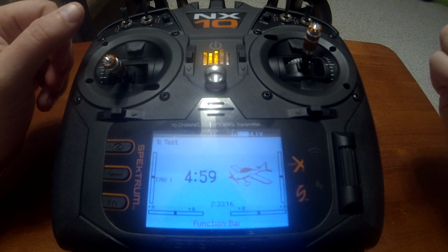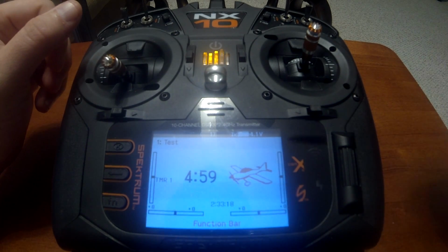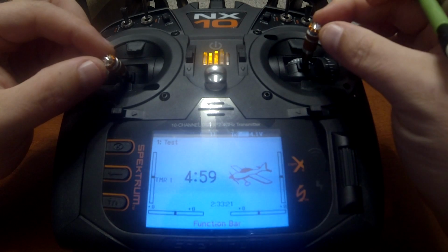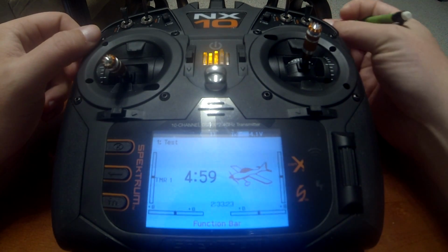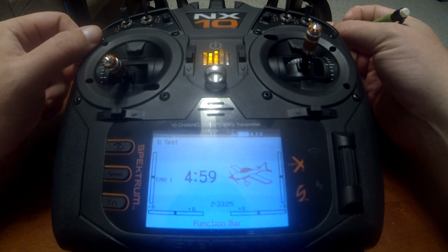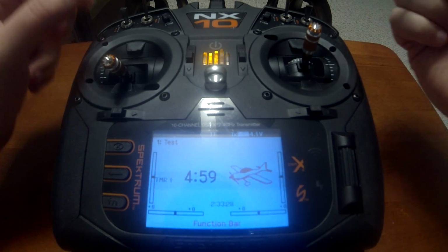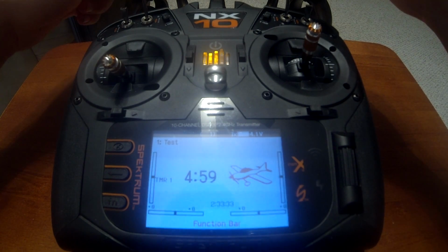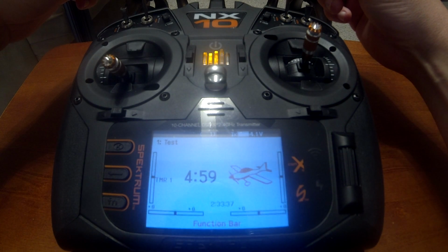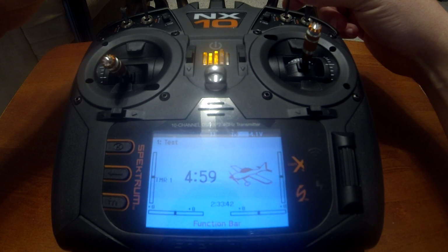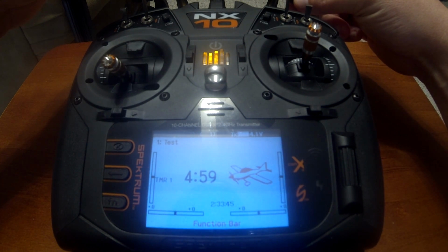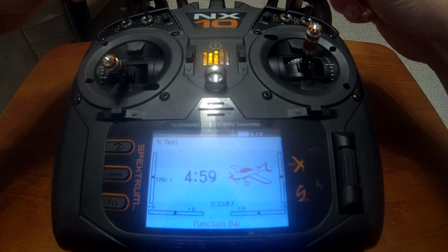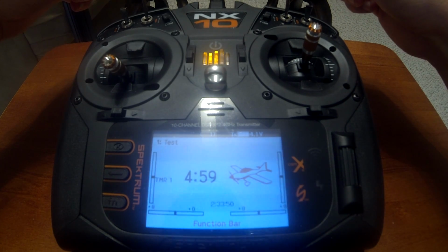If it's an airplane with a prop, before you do this, make sure you remove the prop. Go above 25%, go back down, toggle your switch so that it's in the position for safe mode to be on. Take your airplane and lean it to the left. Your left aileron should go down and your right aileron should go up, because what it's trying to do is correct the plane to level flight. So if you go to the right, the right aileron should go down and the left one should go up. It's trying to correct it from rolling right to the left and be in level flight.